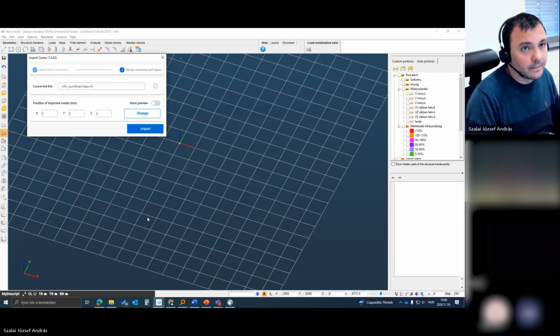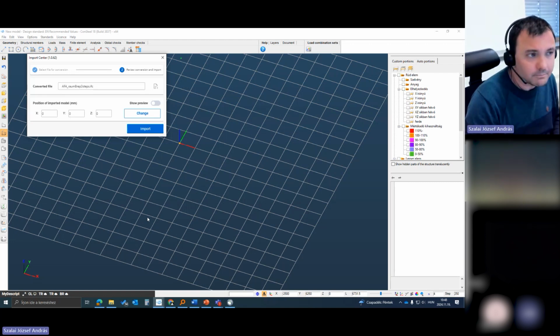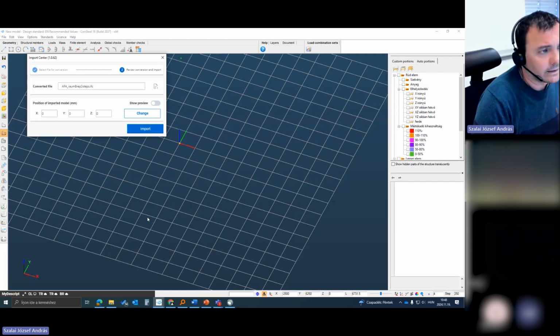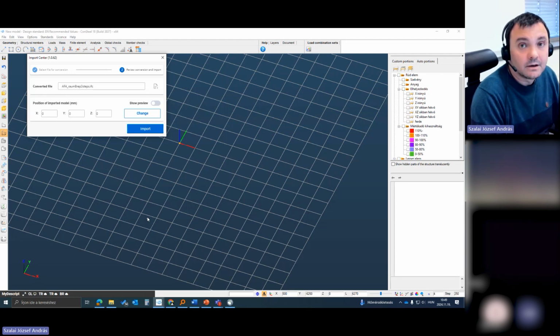The supported objects are the IFC beam, column, member, and plate objects. We can handle B-rep representation and extruded representation. We can handle original or cut length. And we have a section conversion, which is somehow the heart of this model conversion.